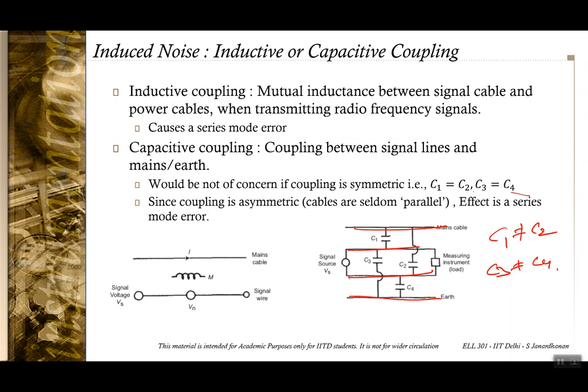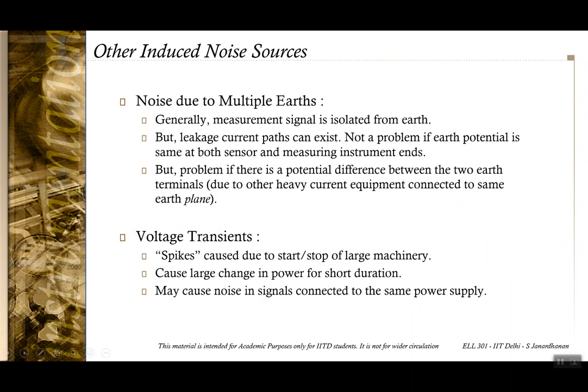Okay, so effectively there is some series mode error that can occur. Going further, other sources of noise are noises due to multiple earths. This is because typically your measurement circuitry is supposed to be isolated from the external power circuitry. However, in practice, this really doesn't happen. You tend to have earths in your measurement circuitry and earth in your power circuitry, and